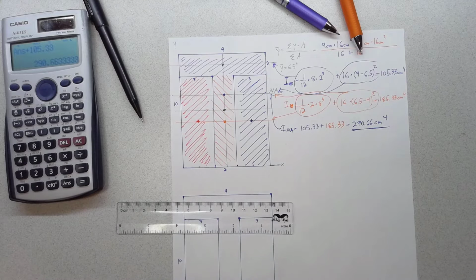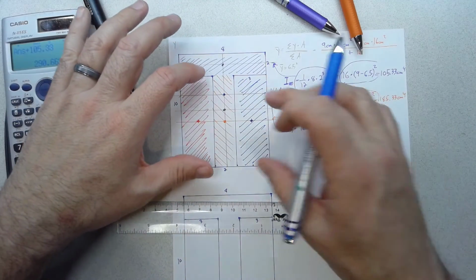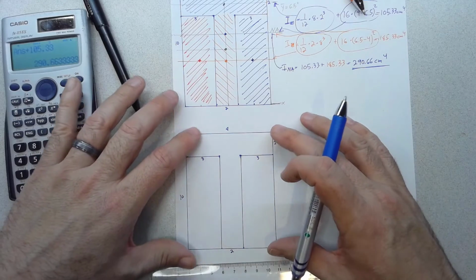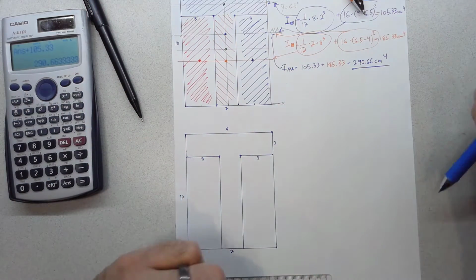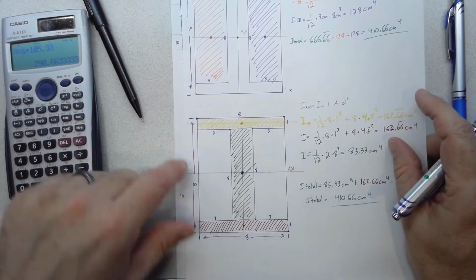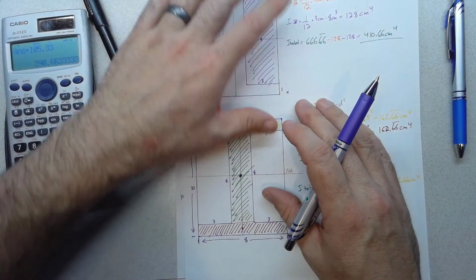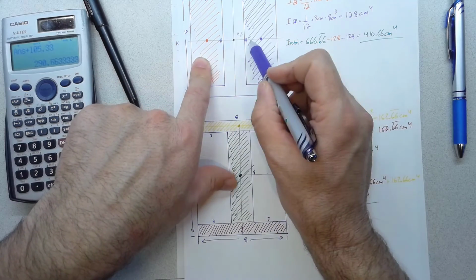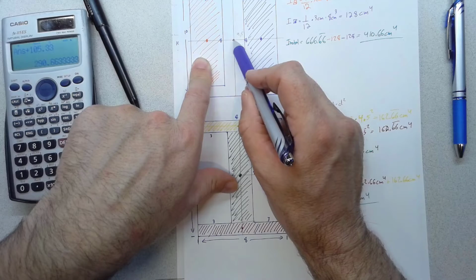Let's look at it. We could have done that a second way, right? So rather than look at the component I's and add these two together, I could have also done it by looking at the overall I and then subtracting these two sides. I just want to make the distinction. This is different than when we were looking at this overall one. Here, I could find the overall I for the whole rectangle and subtract these two directly from that I because they all shared their centroids along the same neutral axis or centroid of the original parent shape. That's not the case now.